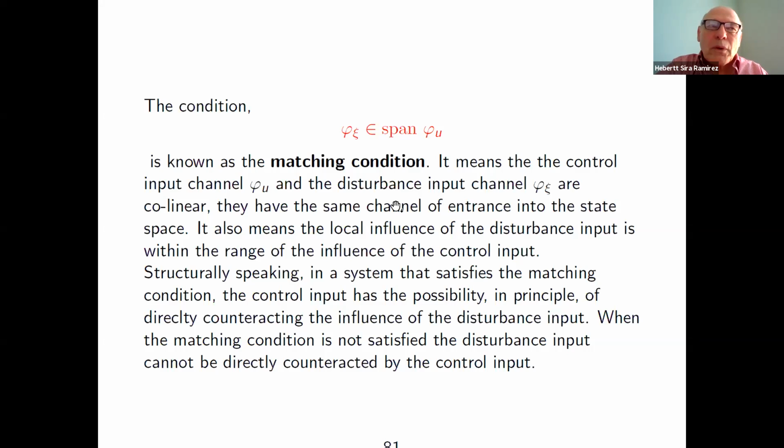Right. But suppose you have some load torques, which are strange, either because of friction or because the moving mass, the rotating mass, has an eccentricity or something like that. And so your mechanical equation is being affected by a disturbance that you don't precisely know at the moment.